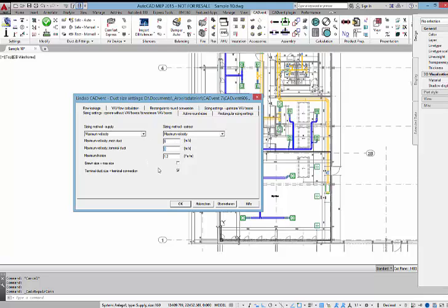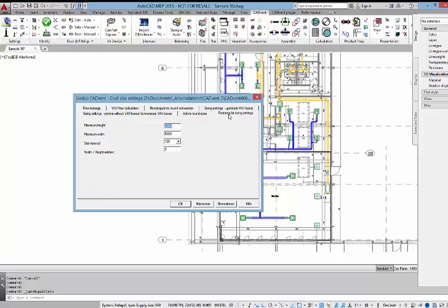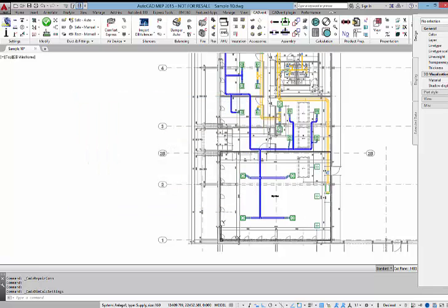But this 3 meters per second can be deactivated if I use this option here, which says that the terminal duct sizes should be according to the terminal connections. So if I've connected a terminal in size 200, then it takes a duct in 200. Of course, this is real life how it will be used. For the sizing, I can activate and deactivate some sizes. You know that air duct systems can be selected in multiple sizes. You can activate and deactivate them if you want them. And we have also sizing functionalities for the rectangular ducts. I will not go too deep into that now. It's just to show what we have in possibilities.